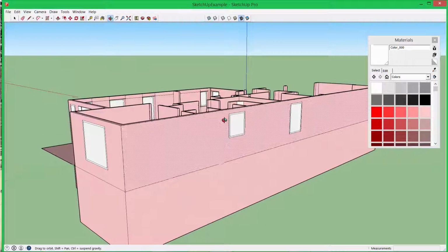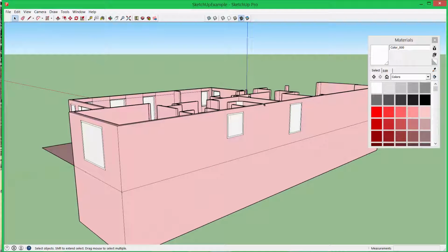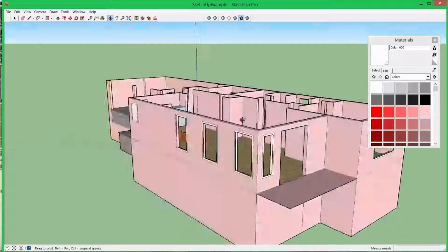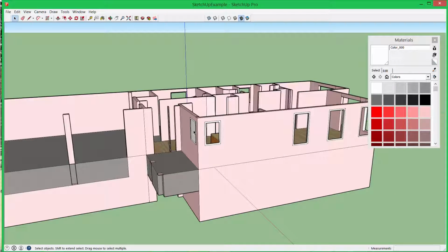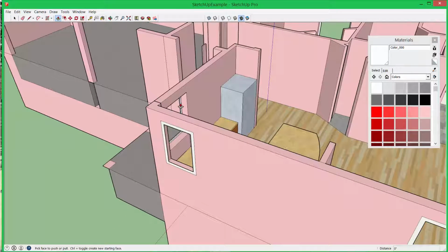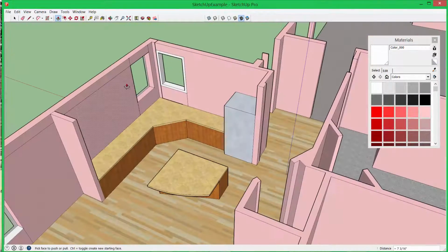And how it does a really nice job of referencing. Then you'll open the windows and just use the select tool, select the middle, and then delete it. Now we've got the openings, and we want to do the push-pull tool. Again, hit the plus mark to make it a solid, and then pull those on to the inside.